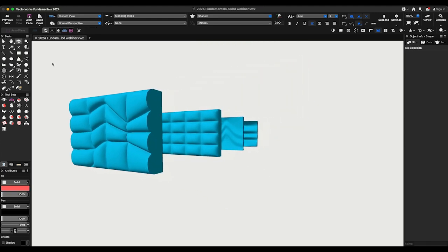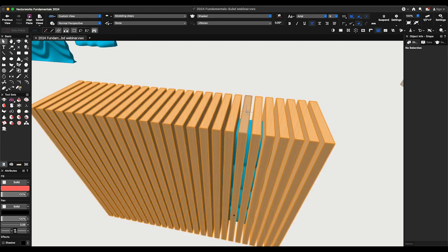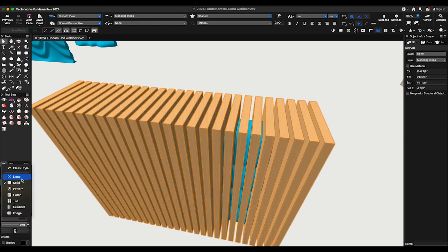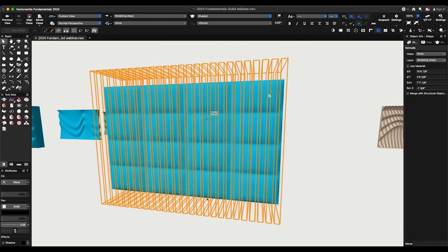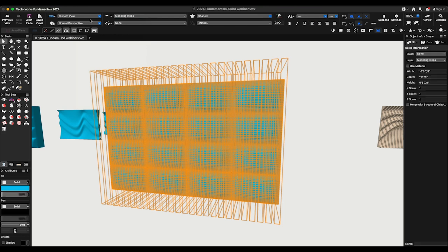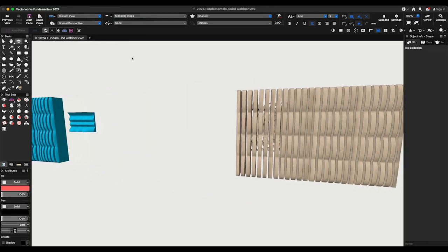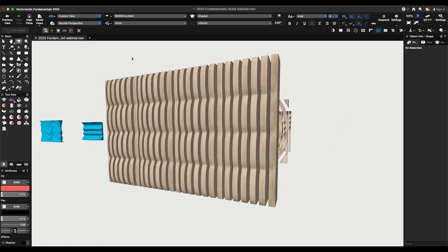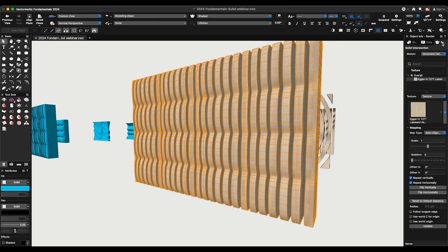Okay, let's move on and I'll show you how we can morph this subdivision object even further. As you see, I have a series of extrudes surrounding the blob. I'll select them both, and from the model menu, I'll select the intersect solid operation. Done. The next move will be to add a texture. Just a matter of selecting the object, and from the info palette, under the render tab, right here is where we can assign and control the textures and its mapping.